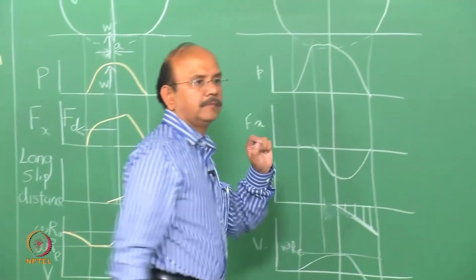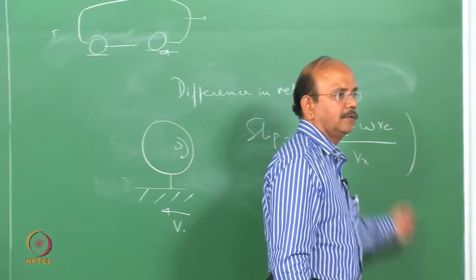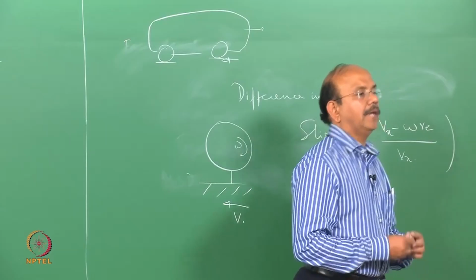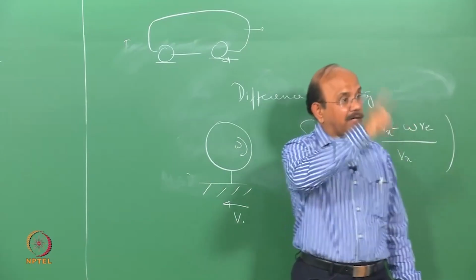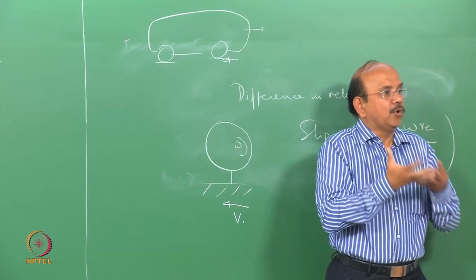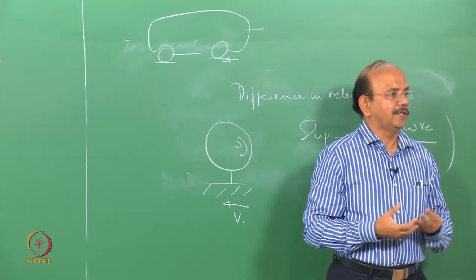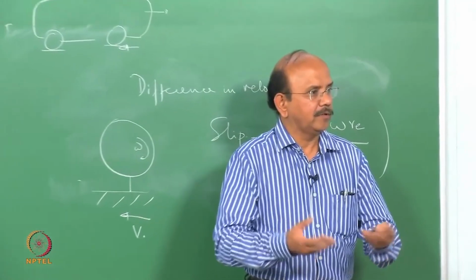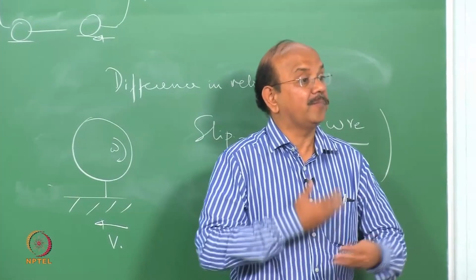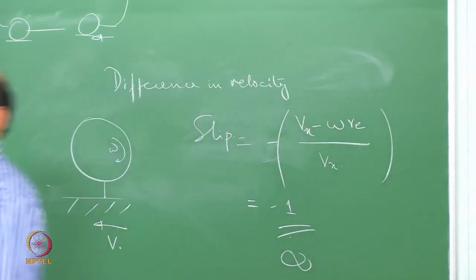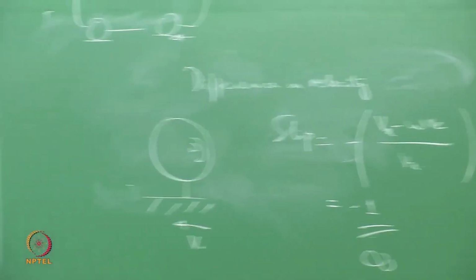Can you explain this again? Infinite. Yeah, because this is equal to 0. No, sir, what is the actual thing like? The wheel is moving. Yeah, here the wheel is rotating. So omega is present, but there is no grip, so the vehicle is not moving. You would have seen this many times. If your wheel rotates but the vehicle is not moving, or in sand, it doesn't develop enough force for the vehicle to move. So that's the condition.